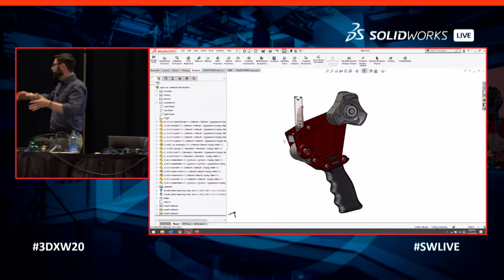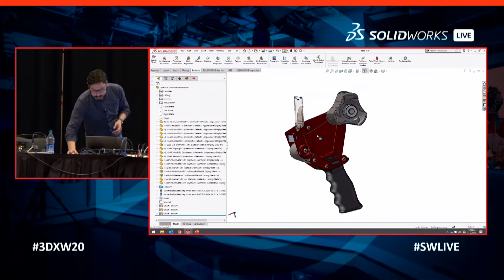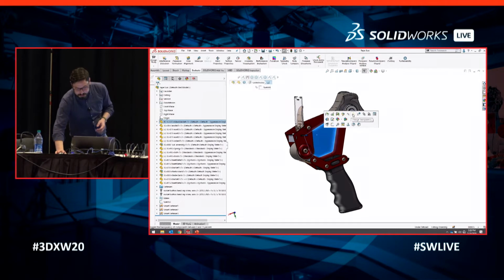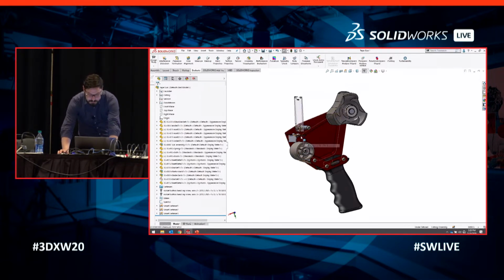A lot of people who need to hide a component to get it out of the way click the component and hit the hide button, wherever it is, a little eyeball, right? And it'll hide that component. But faster than that, you can just hit tab, and whatever you're hovering over will just hide. Okay? Nice and easy.